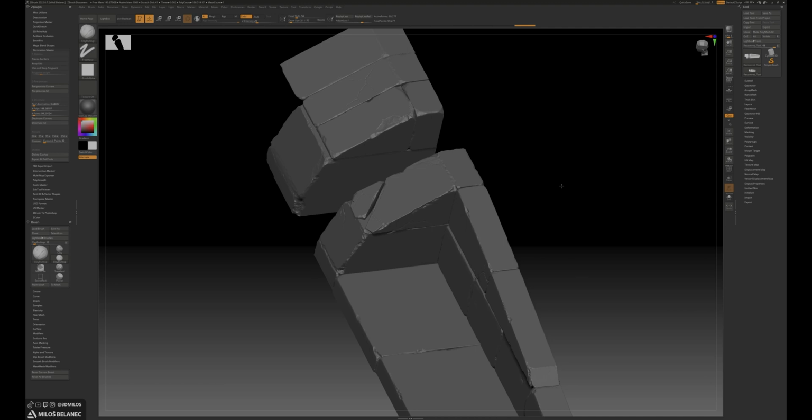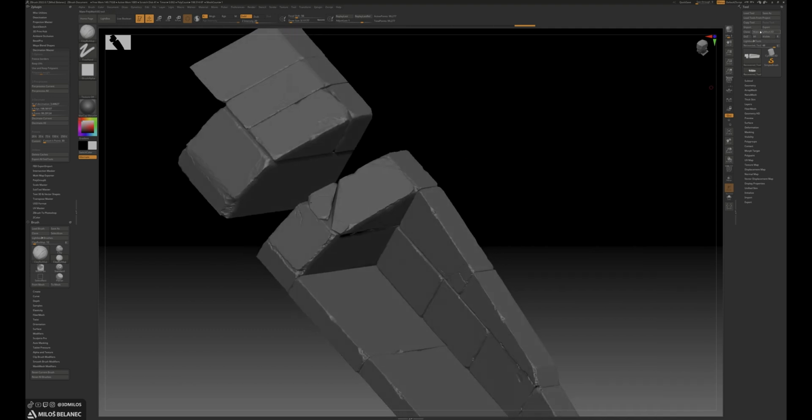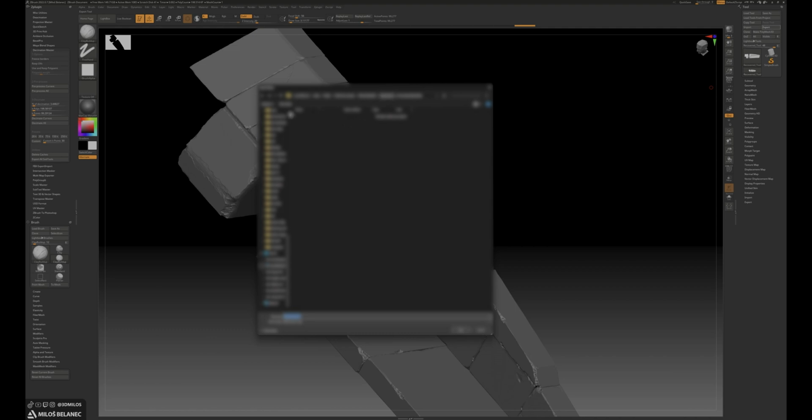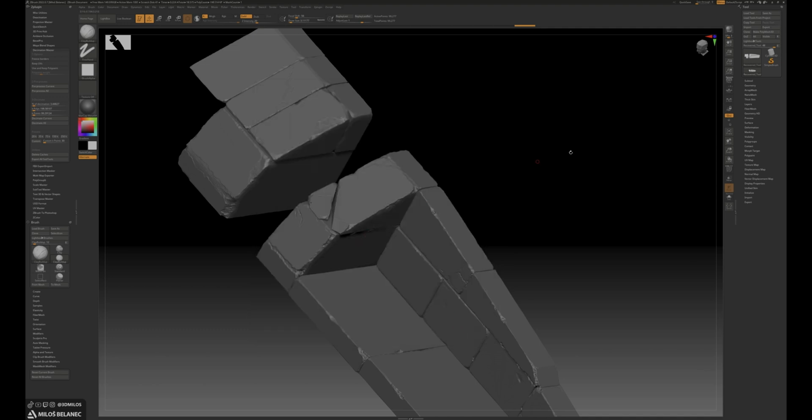And what is good to know, this type of decimation is good for a model like this one. If you want to decimate human parts, something which will be animated with bones, this is not good because in animation the consistent topology is important, and we can talk about it in another video. This triangulation is good for static models which are not deformed by bones or skin deform or something like that. And when everything is ready, we need two models.